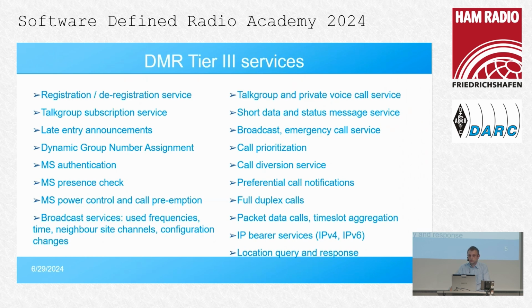Other interesting services are the talk group subscription service, which will be requested normally during the registration or will be released during the deregistration procedure. There are also late entry announcements, which are useful when a radio is switched on and an ongoing call is already happening on the system. The radio will be notified by the late entry announcements and will then tune to the correct channel, even though it has missed the start of the conversation.